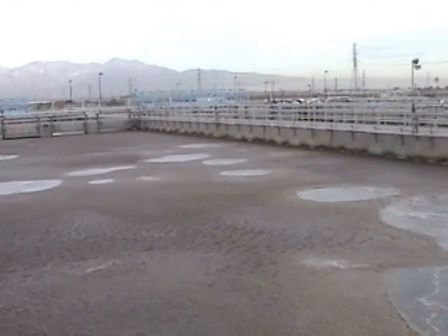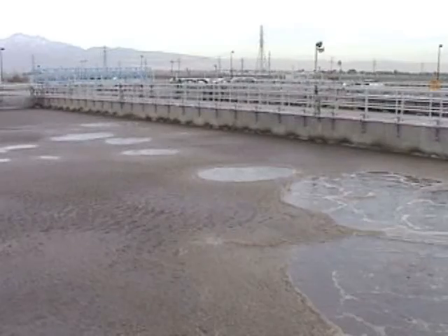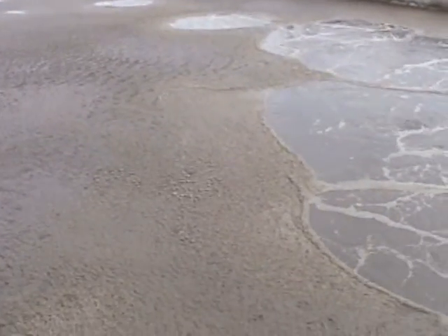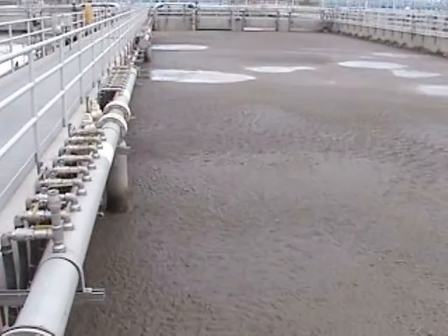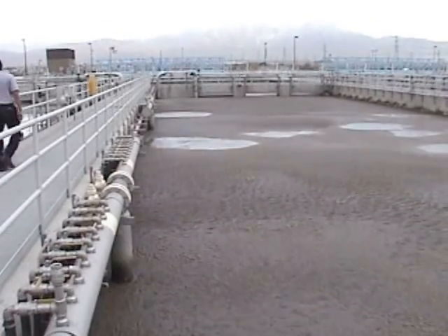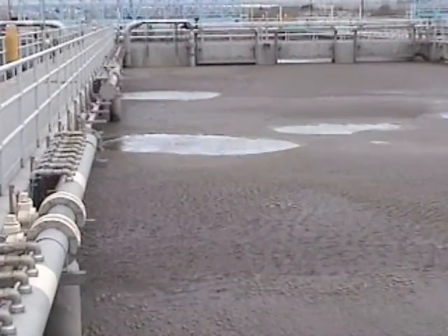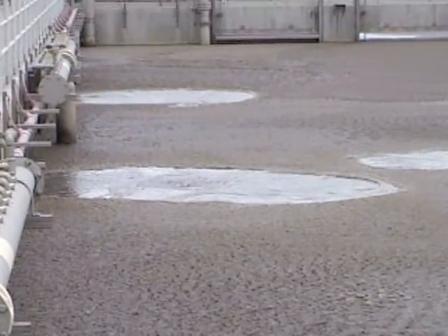If in the absence of air you have organisms like this, Nocardia foam, see, it's a trade-off. You want to get your TIN down, you're going to run a lot less oxygen, but then you're going to risk having foam up on these basins like this. But to answer your question, how we set the air here is based on our TIN values.